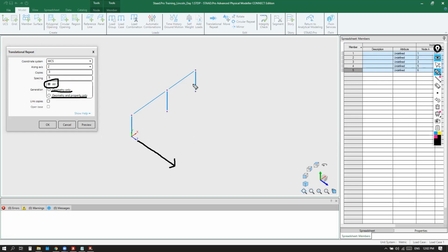Sometimes, in some cases, I want to release, for example, the moment in the beams or in the elements. For example, here in these beams, I want to release the moments, which means I don't want to transfer the moment from this beam to the column. So that's why you can see 3 options. Under here, you have All, which means if you have any releases or specifications.